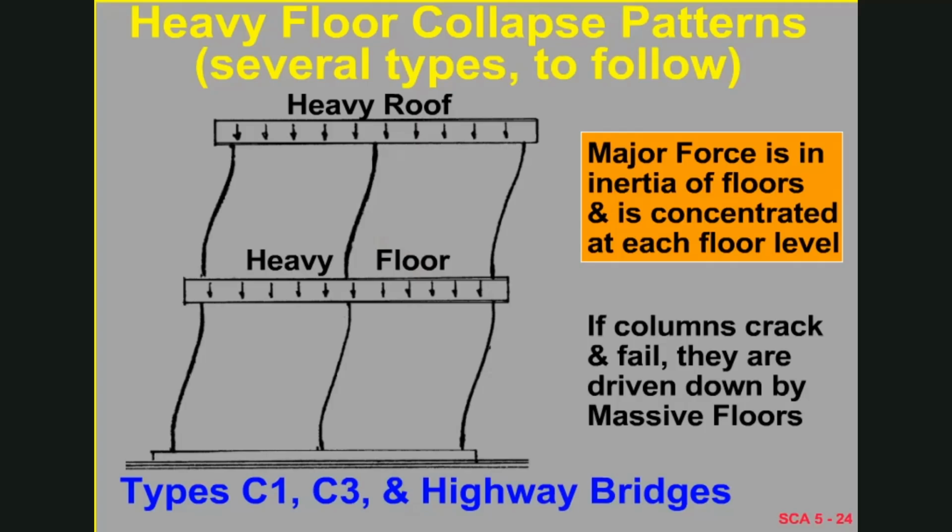In the case of heavy floor, we're talking about concrete buildings for the most part, concrete frame buildings where they don't have many walls, and all the lateral resistance is achieved through the interconnection of the very strong columns and the floor. Outside of California, previous to about 1980, many buildings cannot withstand earthquakes of this type, and so when the joint between the column and the beam is overcome, the gravity forces within the floors will drive the structure essentially into some form of a pancake for the most part.